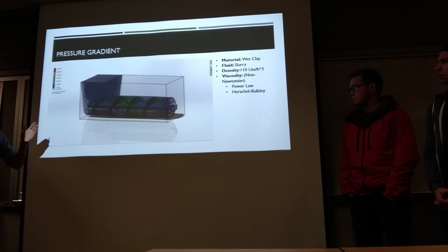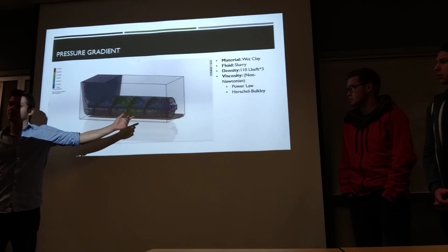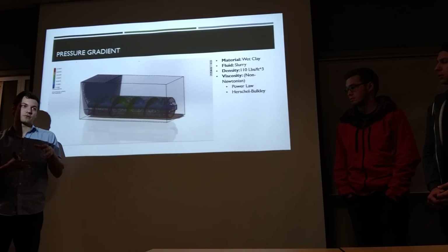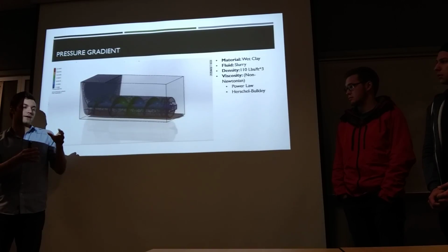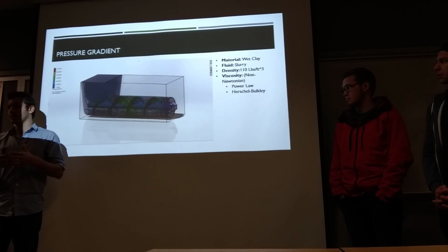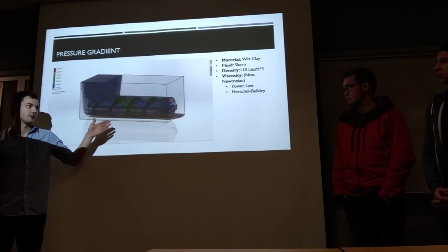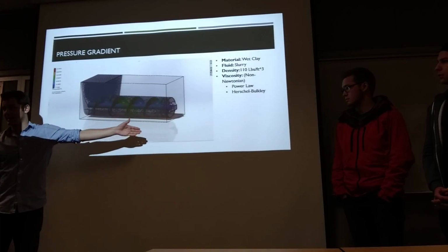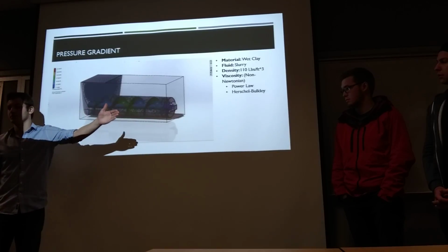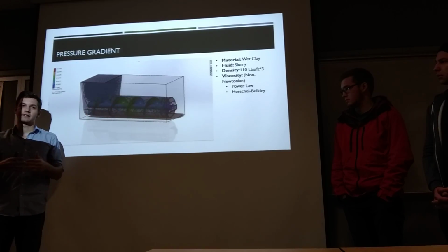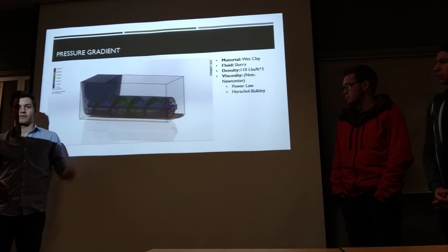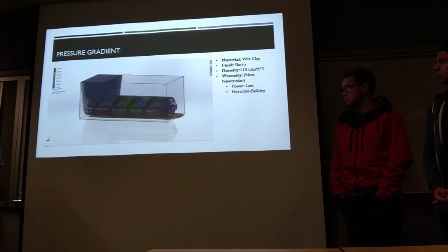The reason you wouldn't see a higher pressure is because the diameter of our barrel, which is what is around the extrusion screw, is not significantly larger than the area that we are extruding out of. We have a 12-inch barrel where the extrusion is 4x10. So you would think this would be high pressure and the material would be shooting out like a water gun. Instead, it's going to be a little bit slower, and that pressure is going to change just before it comes out the die.